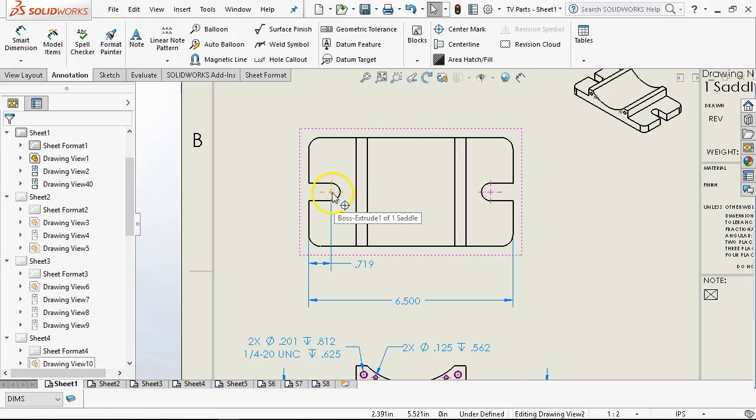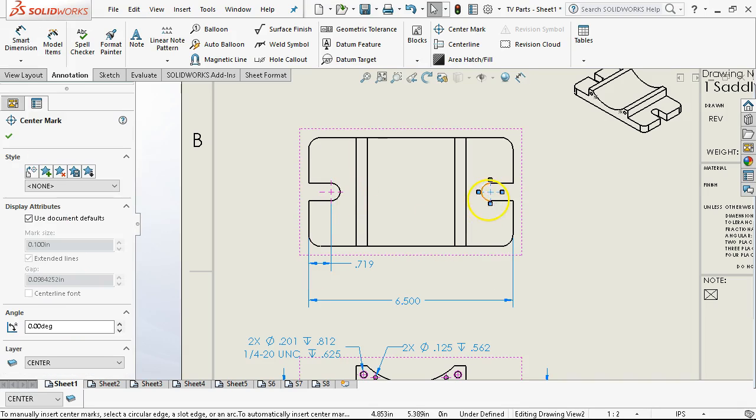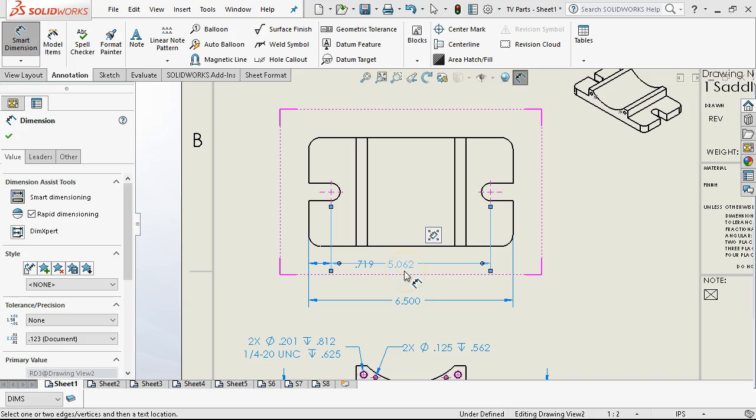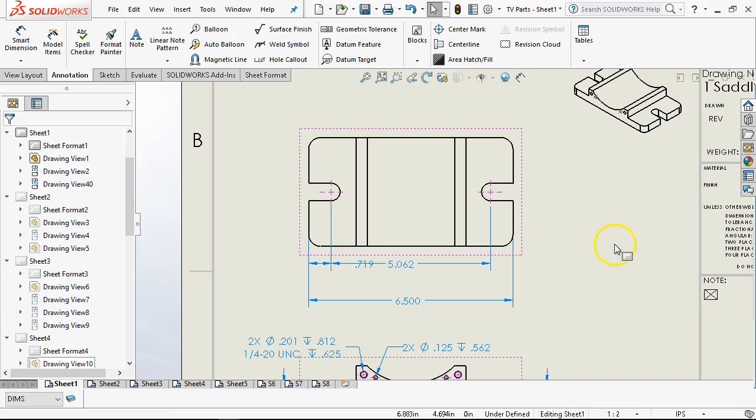As opposed to chain, I can go between the 2 center marks. Well, I guess it would help to be in the dimension. But I'm setting myself up that even at the plus or minus 5 that I put over into the dimensioning, that this whole slot location, the center location, could be out 10 thousandths and still be an acceptable part.